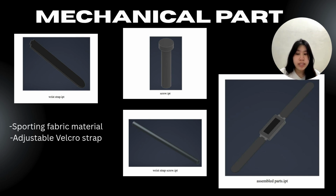The assembly process allowed me to evaluate the relationship between each component and verify the proper placement of electronic elements inside the enclosure. Interference checking and assembly verification were performed to identify possible mechanical collisions, ensure sufficient internal clearance, and confirm that all components could be assembled correctly without modification.